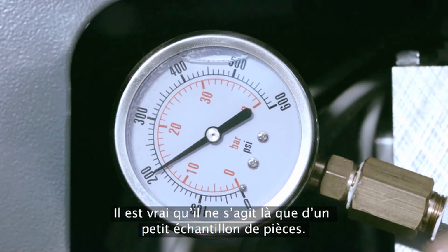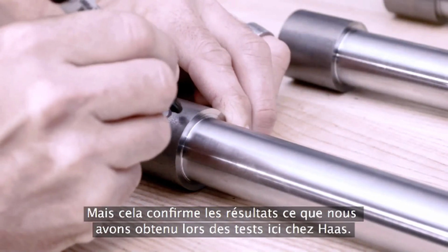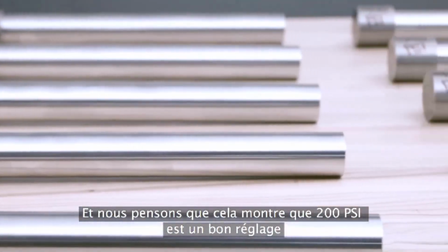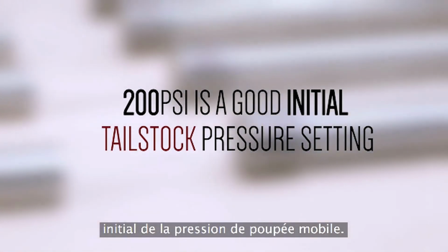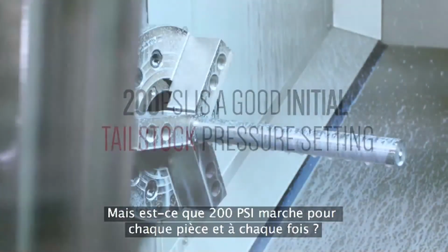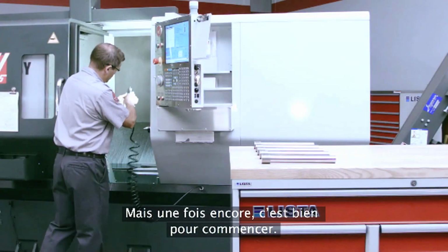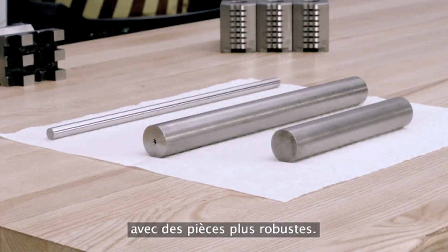Admittedly, this is a small sample of parts, but it supports what we found in testing here at the Haas factory. And we think it demonstrates that 200 psi serves as a good initial tailstock pressure setting. Will 200 psi work for every part every time? Most likely not. But again, it's a good place to start. We hope this section is helpful for the folks who are working with stouter parts.